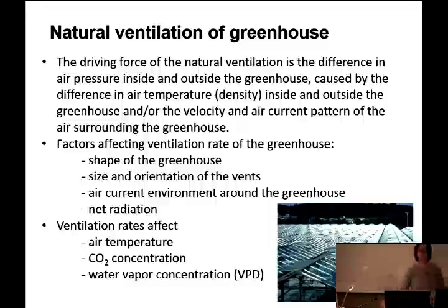If you have an opening in the side and an opening on the roof, the distance between the low vent and the high vent is the driving force, because that creates what we call the chimney effect. That would enhance ventilation. Not only that, the ventilation rate is also affected by the outside environment, how much wind is blowing, and in which direction relative to the vents.